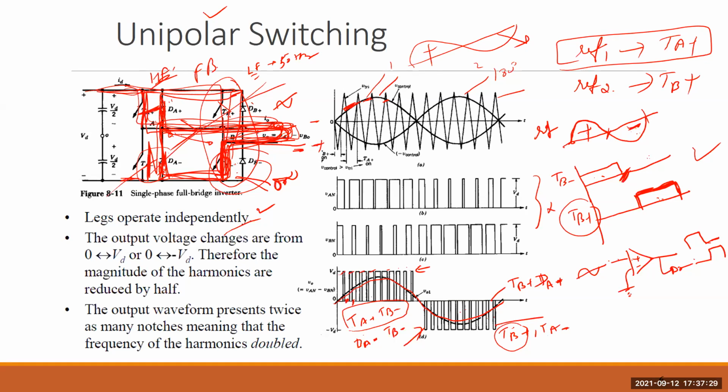But reactive power supply is based on the load and on the phase shifting of the current, not the voltage. Right now, what we are saying is basically voltage, from negative voltage to positive voltage. But reactive power is basically the phase difference of the current with the voltage, and that comes from the load. Any kind of switching will be able to provide that, because once the load has caused the phase displacement, the current phase displacement will come from the source directly.